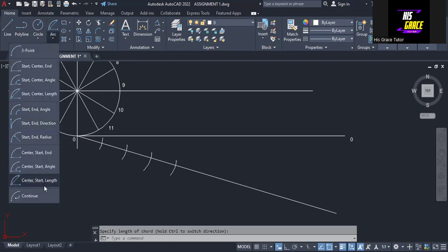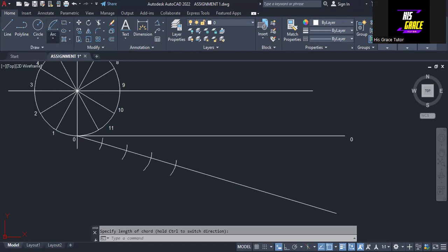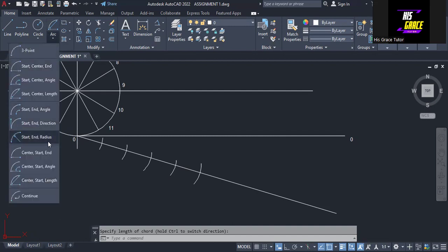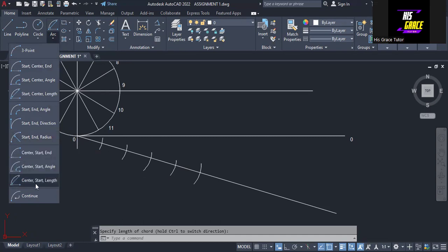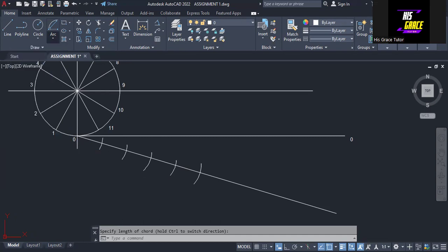The next one, we select this, and then we have this point as center, give it a distance of 15. So we have 1, 2, 3, 4, 5. So we still have 7 more. So we click on this, giving it a distance to this center of 15. So we have this point. The arcs, as you can see that I'm drawing, are drawn in anti-clockwise direction. So give the distance of 15. So it goes like this in anti-clockwise direction.